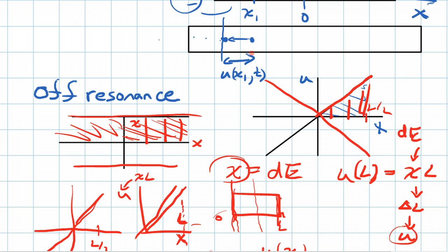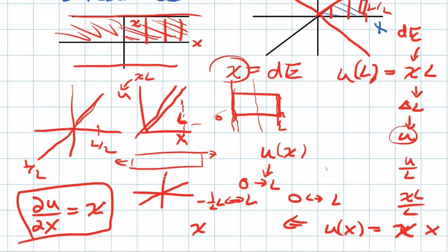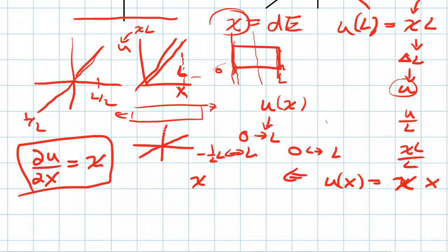The position adds up. So if we have a point here, it moves there because of the piezoelectric strain. By default, it also moves this point over, and then this point also wants to move even more because of the piezoelectricity. So there's two things adding up. There's the initial change of the little atom or little sliver of material before it, and then itself wants to grow and expand due to piezoelectricity, or due to that strain which is occurring uniformly in the material. So this is the strain which builds up in a material.